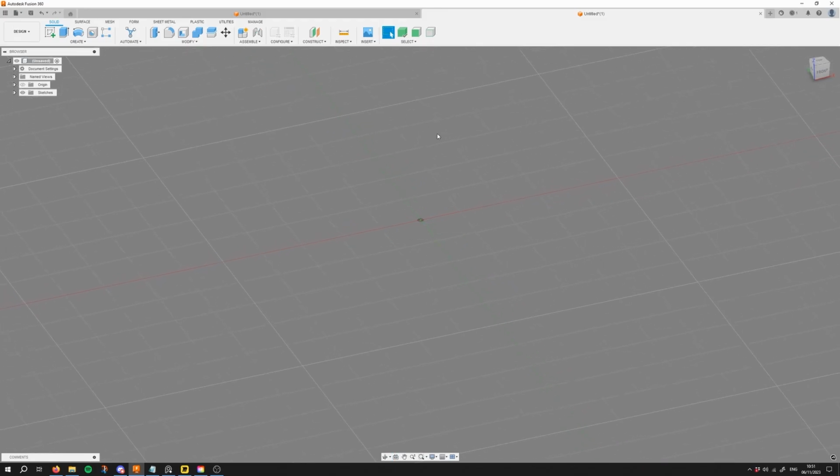One of the things of Fusion 360 is it's a lot of button clicking. It's not like Blender where you have some shortcuts, some pie menus, but we do have a design shortcut. By pressing S on your keyboard, you get this little menu. What this does is just basically a quick access menu. You can basically search any feature in Fusion 360, like pipe, and click this arrow over here, and it'll be inside of the menu.